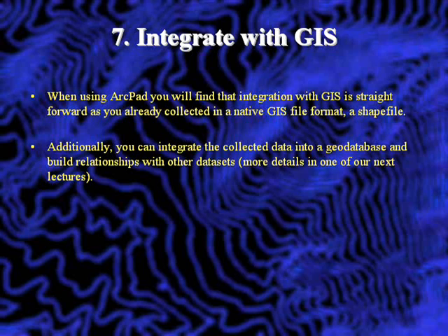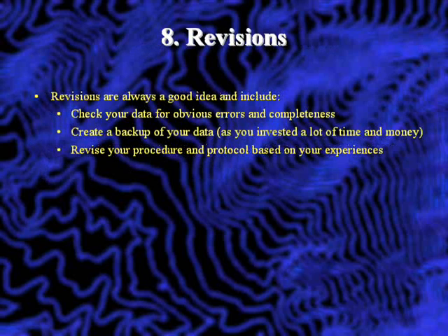Integrate with GIS. Well, this step, since we're using ArcPad, is pretty straightforward because you are using shapefiles directly. Additionally, you can also integrate your collected data into a geodatabase and build relationships with other data sets that you might have in your geodatabase. But again, what we start from is a shapefile.